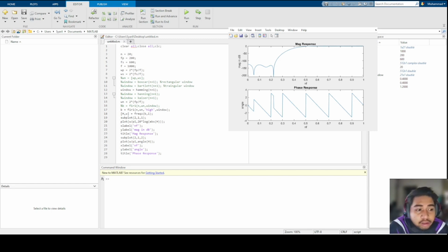The Hamming window is a taper formed by using a raised cosine with non-zero endpoints, optimized to minimize the nearest side lobe. The number of points in the output window. If 0 or less, an empty array is returned. When true, generate a symmetric window for use in filter design. So I will do Hamming.